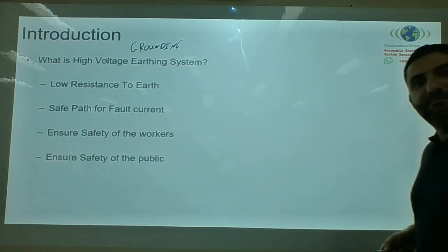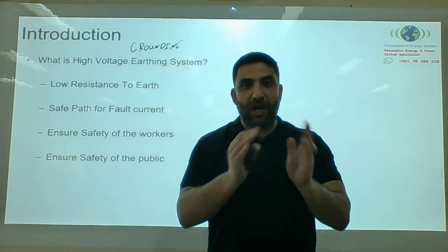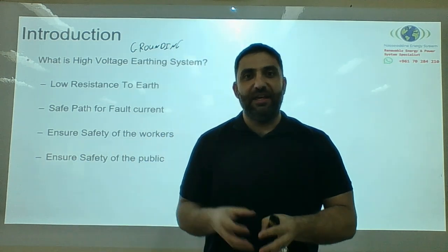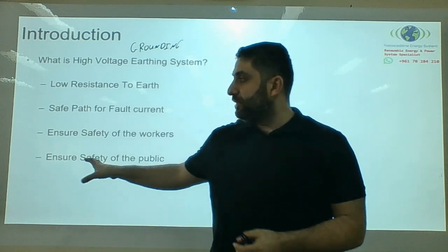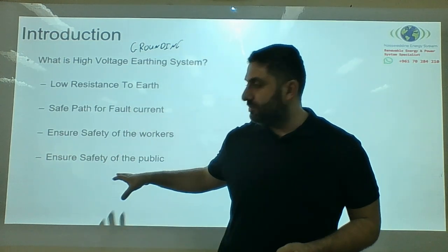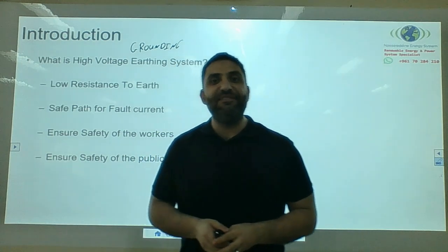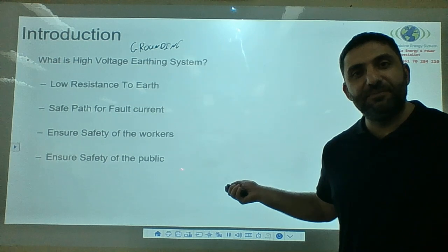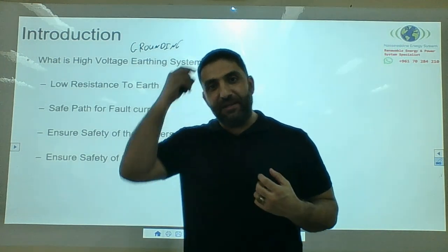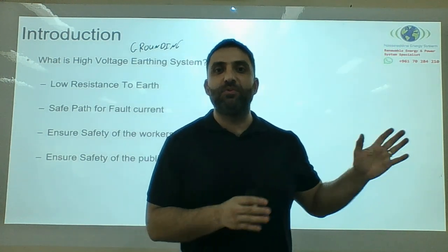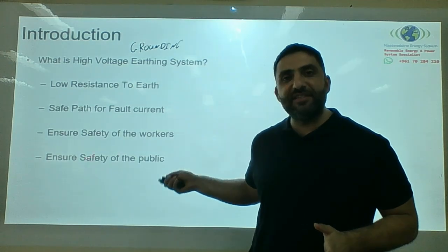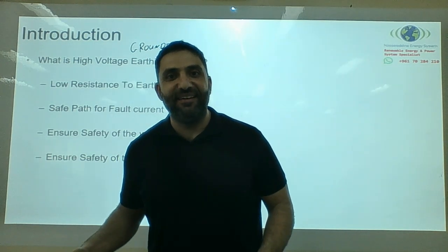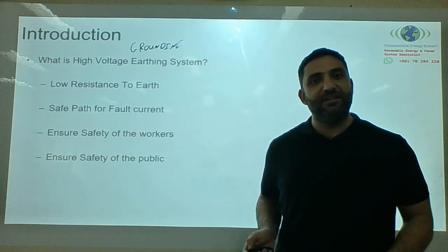Safety of the public. Because now the high voltage infrastructure, as we spoke, for a substation or transmission line in close proximity to the public, I need to make sure that under any fault, the safety of the public is always maintained. That's very important. I spent a lot of years of my experience working in Sydney, and I know there is a Work Health and Safety Act 2011 that puts responsibility on the designer if you don't make sure there is adequate safety consideration.